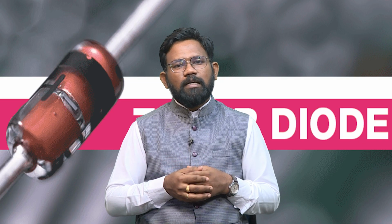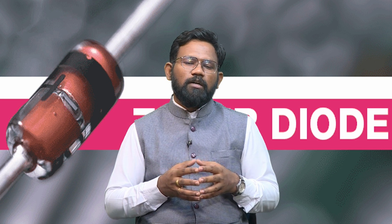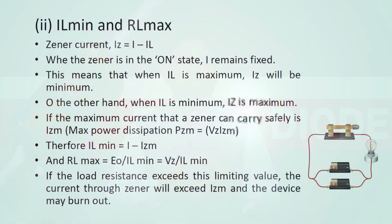Now, this condition is for a fixed value of source and variable resistance. The second condition is when the current is minimum and the load resistance is maximum. The Zener current here is Iz equal to I minus IL. When the Zener is in the on state, I remains fixed. This means that when IL is maximum, Iz will be minimum. On the other hand, when IL is minimum, Iz is maximum.